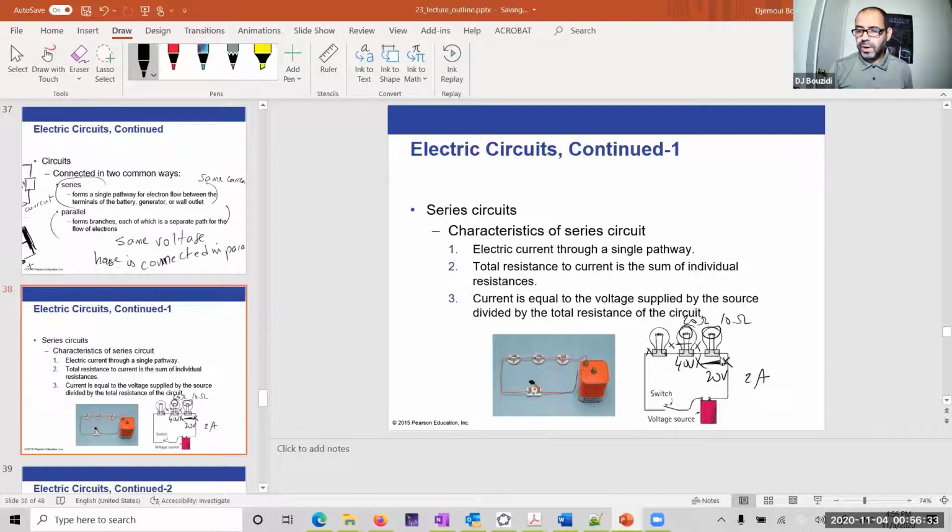Let's say, for the sake of argument, this is 5 ohm. Then this is 5 times 2, which is 10 volts. So the entire voltage drop is 20 plus 40 plus 10, which is 70 volts. This is your 70 volt battery that provided that. So the voltages may or may not be the same. It depends on the resistance though, okay? So that is the series circuit.